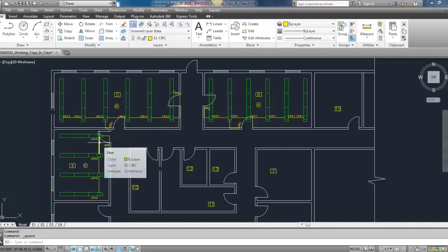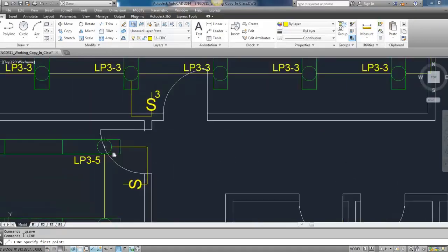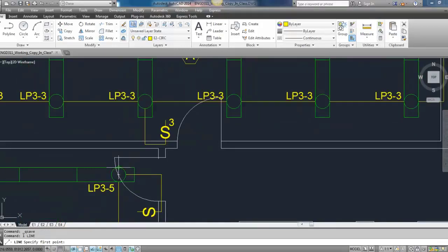That's how it's going to work: you're going to have 3 circuits from each phase, A, B, and C, sharing the same neutral, therefore they have to be on the same conduit path. So I'm going to start at this end over here, the one furthest away, and take a connection from this particular conductor. I'm going to run it in this direction and connect it using 45 degrees.